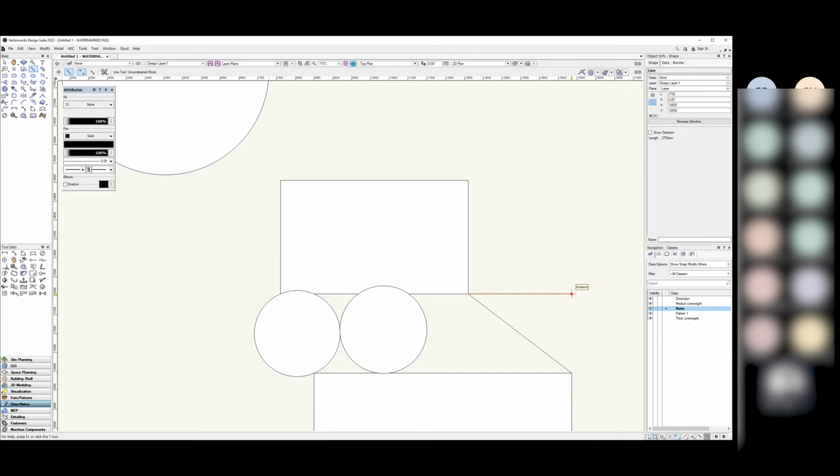Now it gives me something to snap to. So that's what smart guides does, or smart points. The ones I have are snap to object, snap to angle, smart points. You might want to turn the smart points off once your file gets really, really heavy.